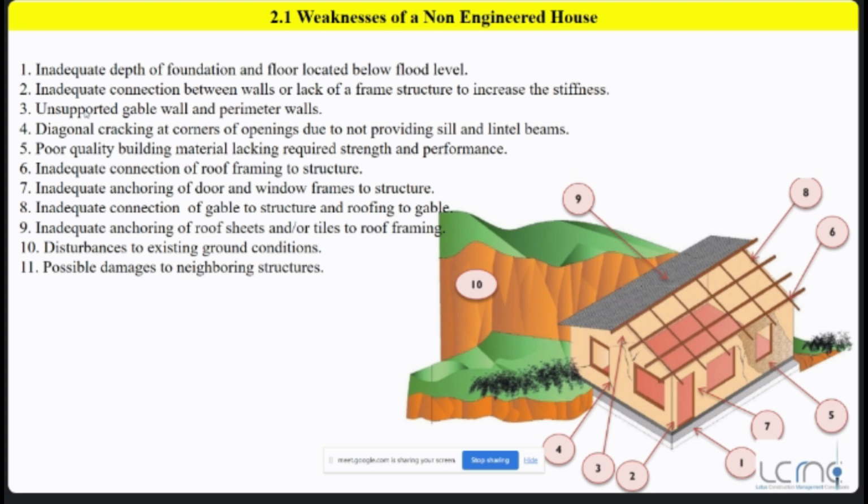And also, if your wall height is very high, if the area of the wall is exceeding 9 meters squared, definitely you need to provide some stiffness structures. Otherwise your stiffness will not be adequate to bear its own weight. Okay, so that is that.